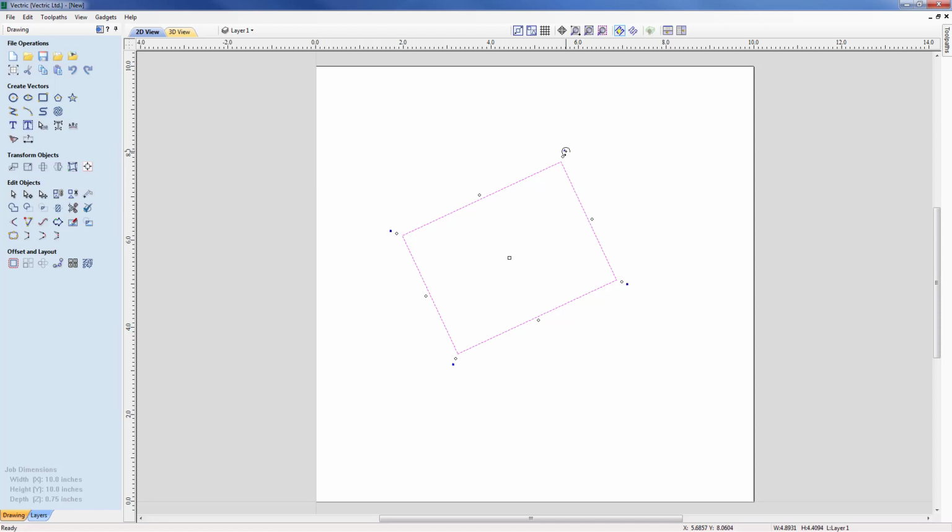Therefore, if I wanted to move it in the clockwise direction by 30, I can just type in -30, return, and that will rotate it by 30 degrees in a clockwise direction. So anti-clockwise is default, clockwise we just use a negative angle. So that quite simply shows us taking the rotation anchor and using the keyboard entry to specify the rotation rather than having to come up to the rotate objects command. And for that now we've covered all the items within transform shortcuts, and please refer to the help notes because all the options are displayed there, of which we've shown most of those within this presentation.